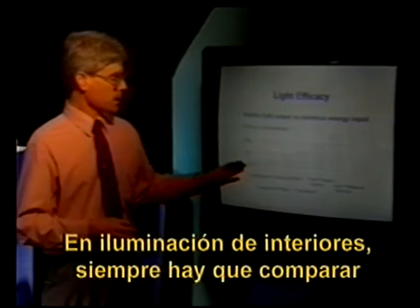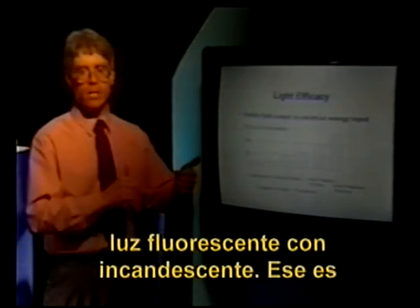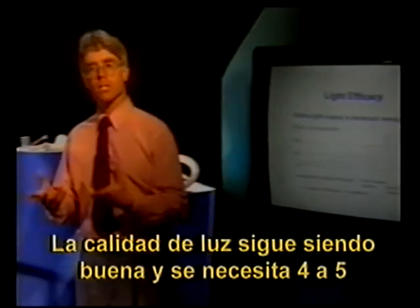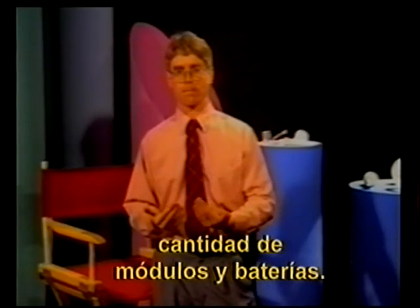But the clear comparison that we have to draw all the time in terms of indoor lighting is comparing fluorescent lighting to incandescent lighting. That's a changeover that you can always do. You'll still get good quality of light, and the amount of energy that you need is maybe 4 to 5 times less. So again, the number of modules and batteries you need are going to be less.